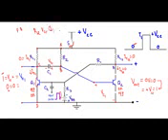That voltage will be applied between the base to emitter junction of the transistor Q2 as the capacitor discharges, and when its voltage is greater than 0.7 volt, that voltage will drive the base to emitter junction of the transistor Q2 in forward bias. Therefore now our transistor Q2 will be in on state.